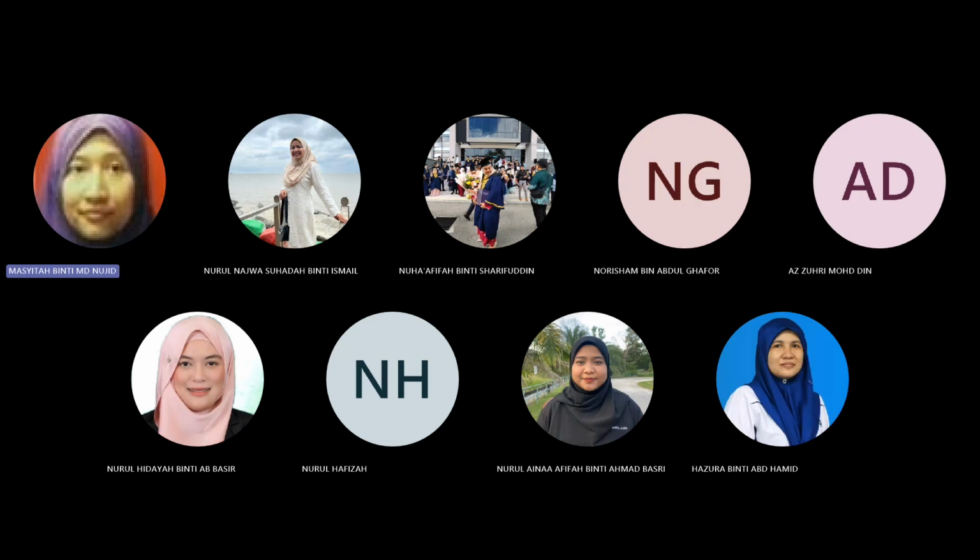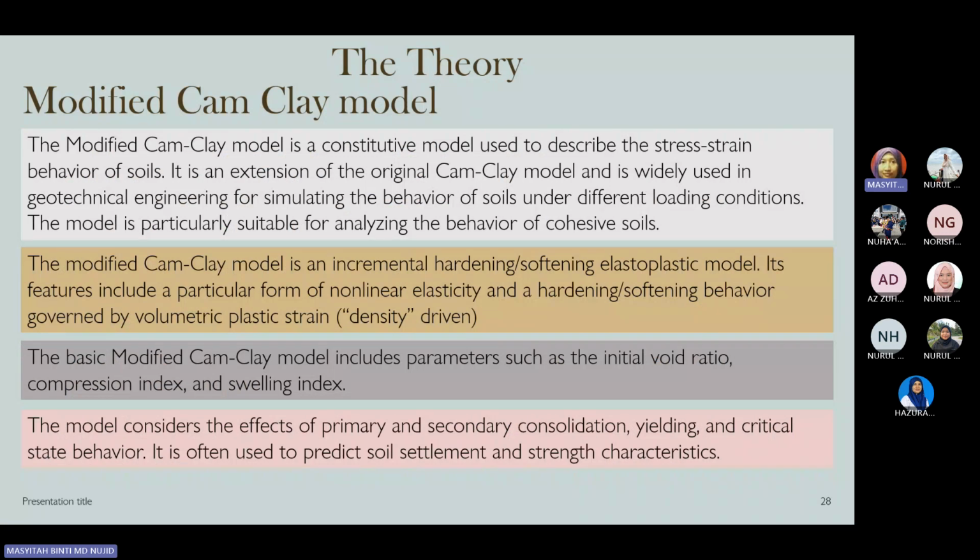It is to define the long-term stability, for example, of a slope. The slope will fail after years have passed since it was constructed, meaning that after a long period of time, the stability of the soil, in terms of shearing, decreases. But in contrast, for deep excavations, the critical point is during the construction, which means the short-term stability, because it increases the effective stress.